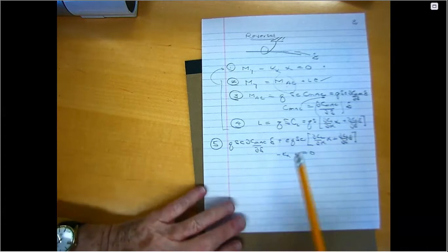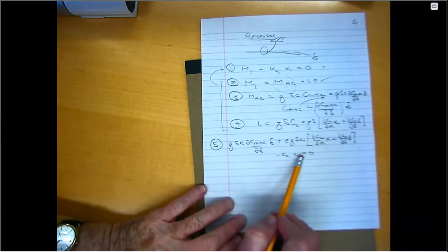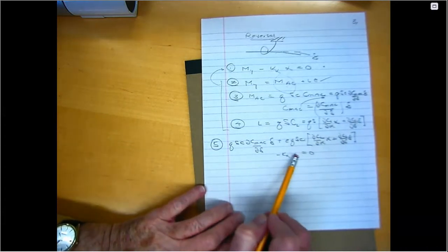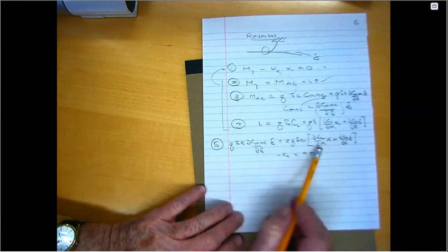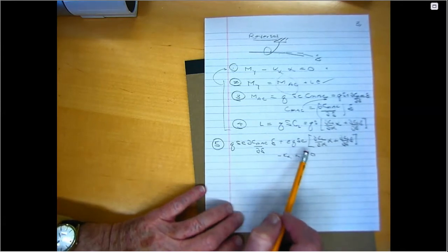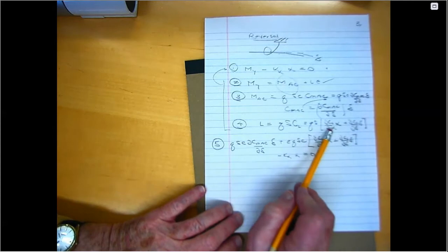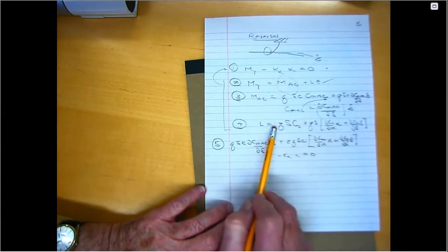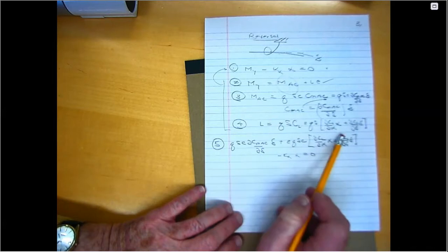Now, what can we do with this equation? Well, given delta, we can determine alpha, right? It's a linear equation, so that's not going to be too terribly difficult. So what I could do is take this equation and solve for alpha in terms of delta. It's going to be a linear relationship, obviously, since it's a linear equation. Put that in the expression for lift, and determine the total lift entirely in terms of delta, having eliminated alpha.